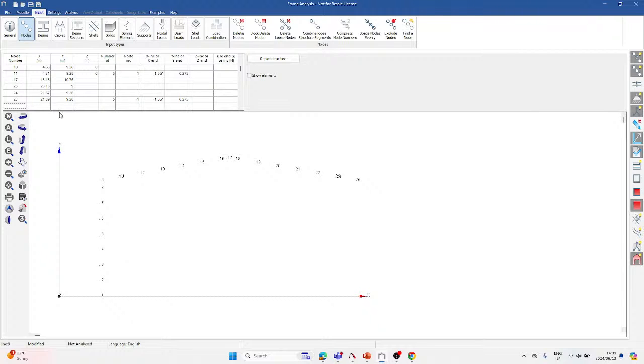So now the next thing to do is for us to define the column on the right hand side. So the last point at the bottom of the column is going to be node 33. So it'll be 23.15 in the x direction, and then it'll be 0, 0, because we're defining that bottom node over there. And then in between the column I want 7 extra nodes, because we are moving from node 33 to node 26. It will be -1 for node increment, and then I want them spaced 1.2 also in the y direction.